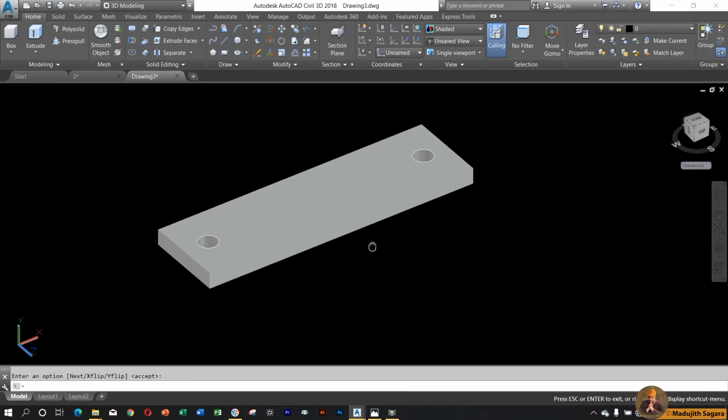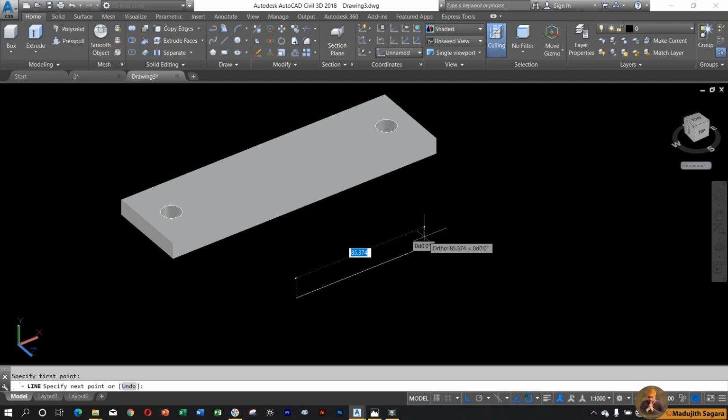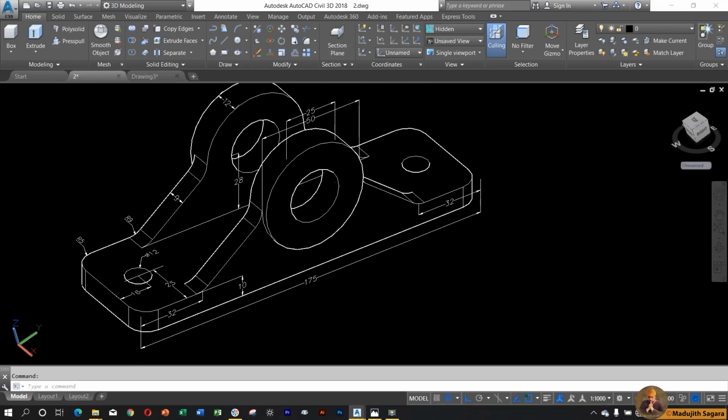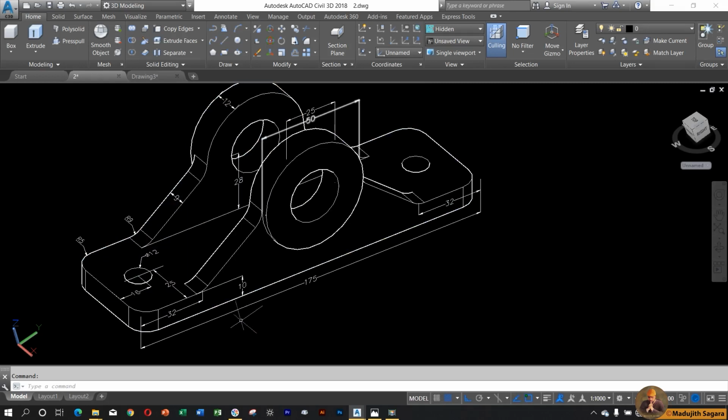How to draw? That is very easy. Select the line that is here. Then you can easily draw. Better to turn this auto on. Then what is the distance of our line? That is 111. Now make it okay. Now that is it. Then what is the height of our line? Actually, we don't need to complete this triangle. We want only this one. The reason is at the end of this 28 distance, perpendicular to the 111, we have two circles. They are the circles with 25 diameter and 50 diameter.